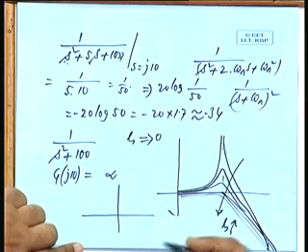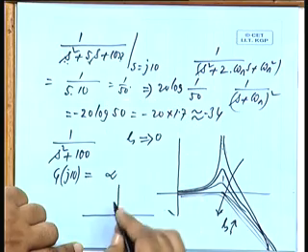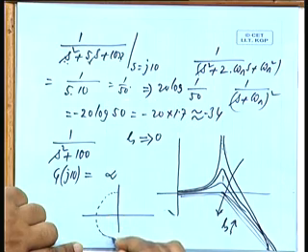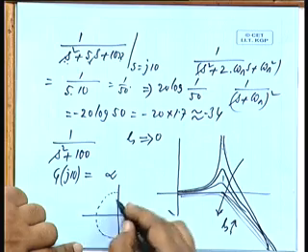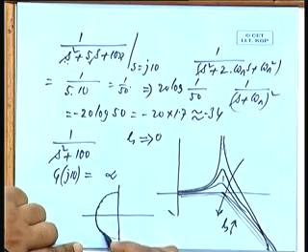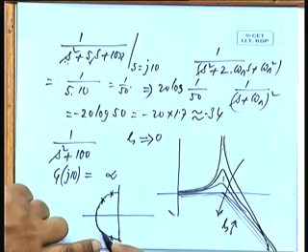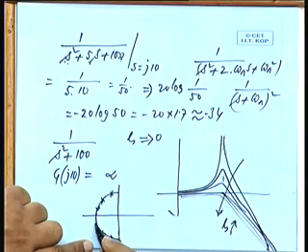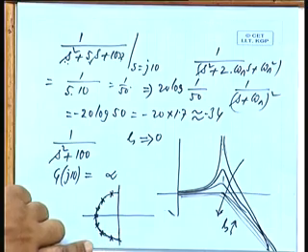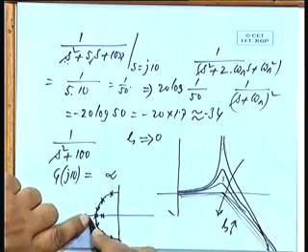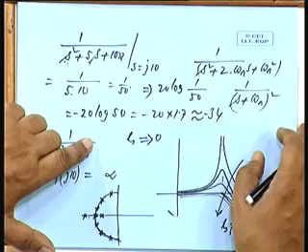If you remember, for different values of zeta, if you calculate the roots of this quadratic, we will take it up in the next class, how the roots travel and how they change. For different values of zeta, the complex pair of roots will move like this, and then this is the point when they become equal. If you increase zeta beyond this, the roots will be real but separated. You will get two distinct roots. We will take it up in the next class, and then we will see how to make the phase plot from the gain plot.